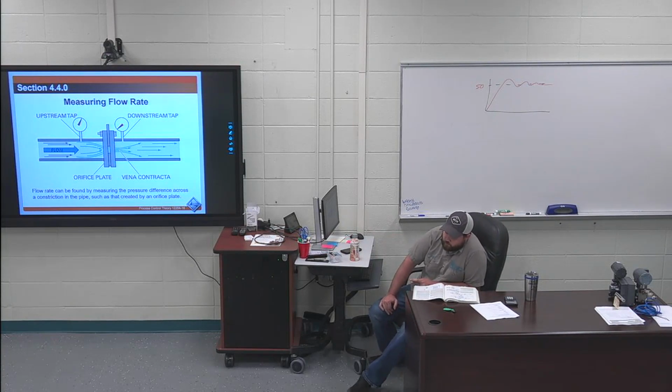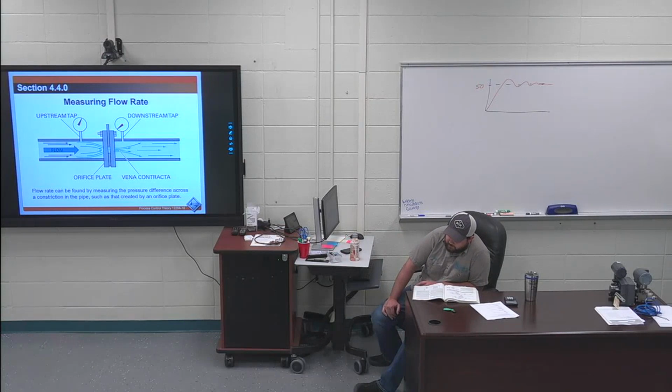A variable head flow meter measures pump discharge flow. The differential pressure is created by the flow nozzle. A locally mounted flow transmitter senses the differential pressure and sends a pneumatic signal to the square root extractor. The square root extractor converts the differential pressure signal to a linear flow signal and transmits the flow information to an indicating flow controller, or FIC. The controller compares the actual flow signal to the desired flow or set point. If a difference exists, a change in the control pressure is produced that actuates the bypass valve.